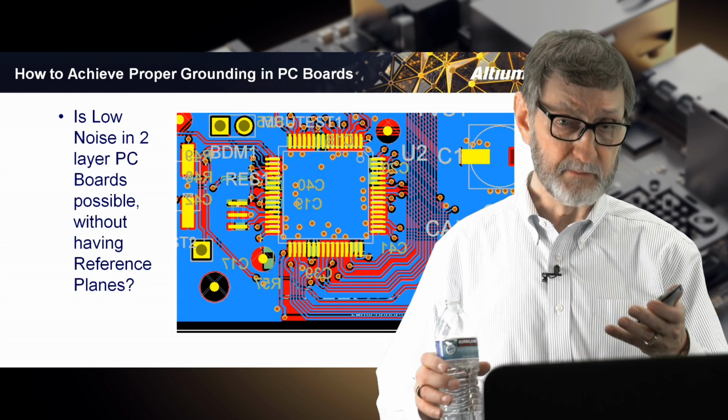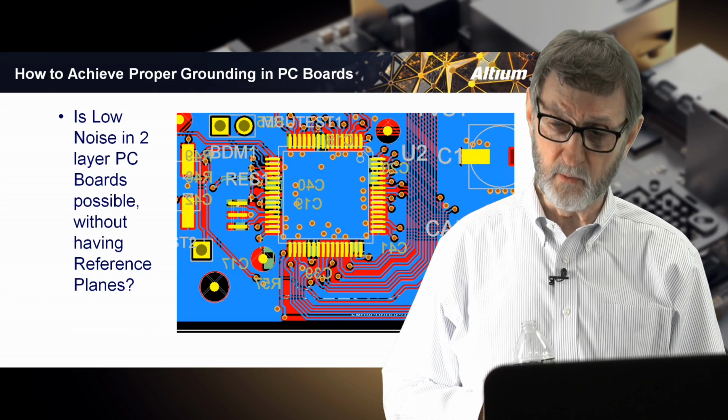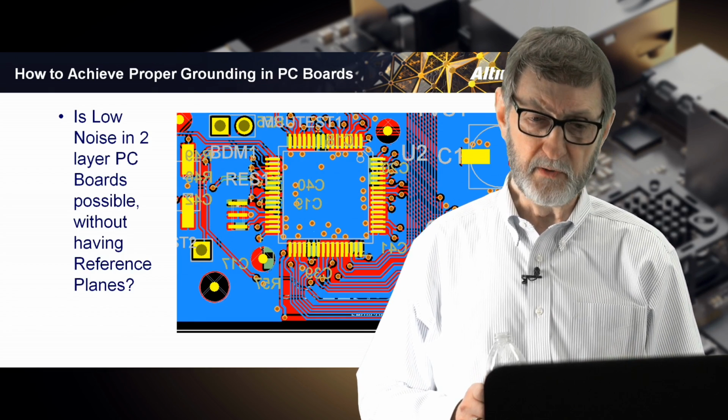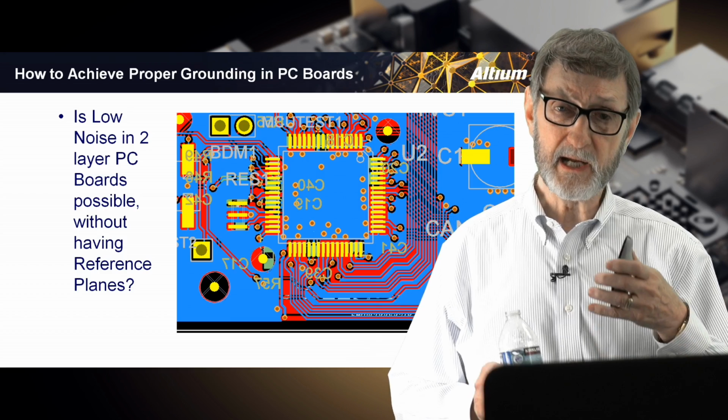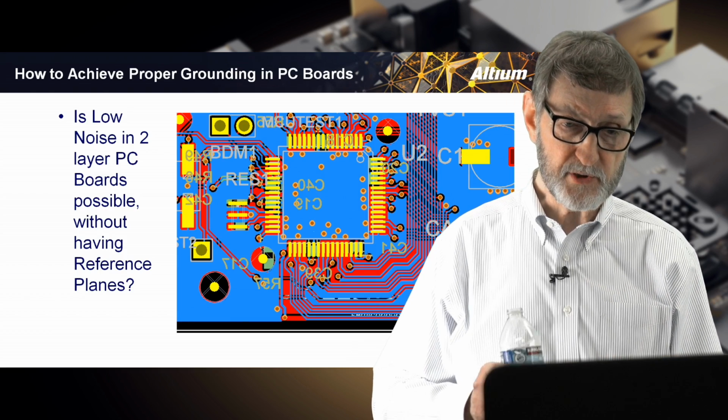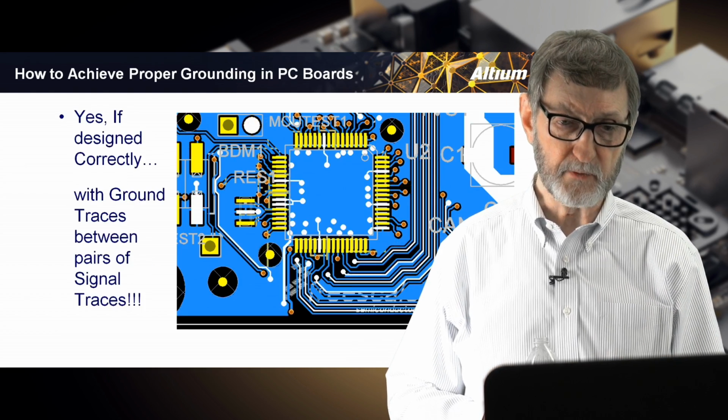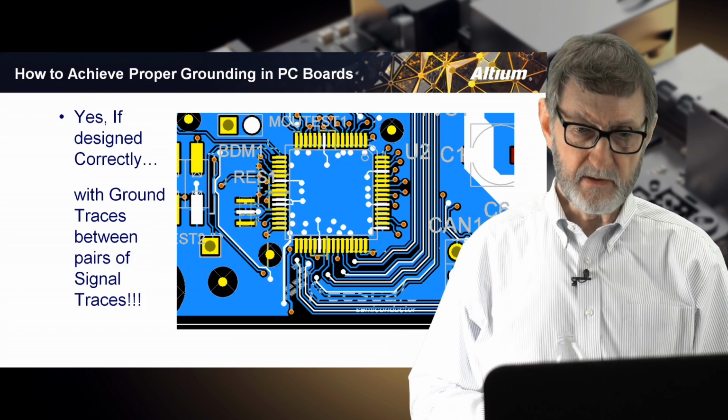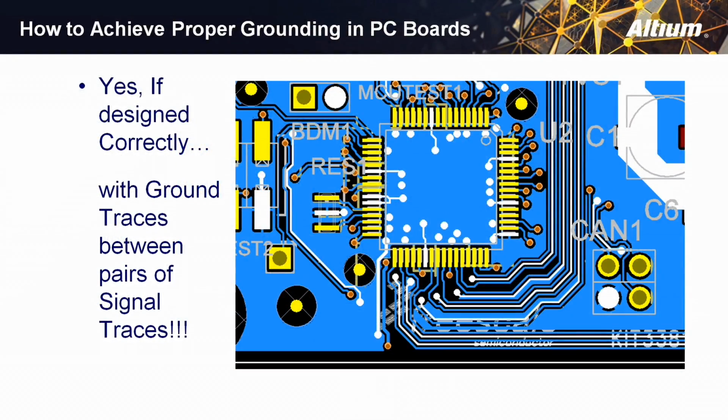They contacted my friend Dan Baker, whom I mentioned a little while ago. He works in the automotive industry, and he had his guys redesign this board. I'm going to show you just the top of the board after it was redesigned. They rerouted all the traces so that all of the white traces you see in this figure are ground lines that were routed next to the signal lines.